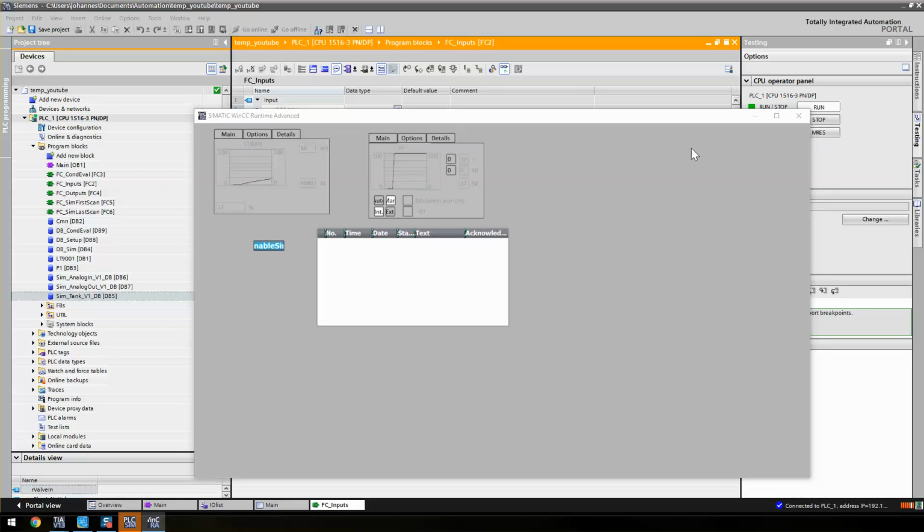If we turn off the manual input, does the level decrease? It does. And if we give it a set point, 50% maybe, put it in auto. Yeah, that's going to take forever. 20.